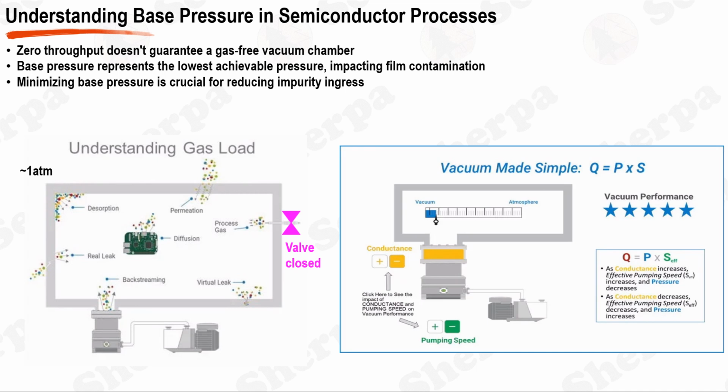as the base pressure. The base pressure is the lowest achievable pressure with the current pumping speed, and it is desirable to minimize it to reduce film contamination during thin film processes. A high base pressure implies higher impurity ingress, even at operational pressure levels.